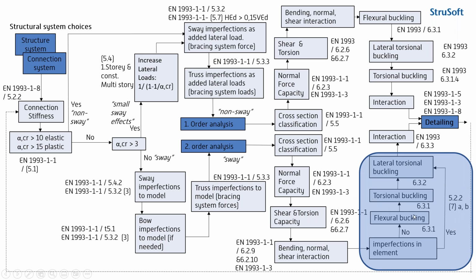So the thing is that if we have a beam model, if it has all the deviations, it's curved already in the analysis model, and it has a torsional stiffness, so it can torsional buckle. You don't have to do them if you have put them in your analysis model, but you should include torsional deformations and also bow imperfections in your model to actually skip these checks.